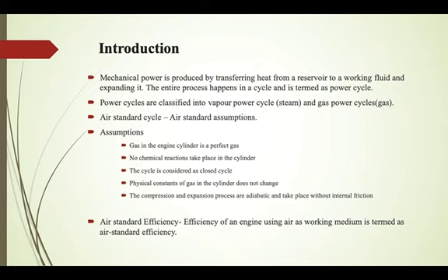Another term is air standard cycle. Air standard cycles are those cycles which work with certain assumptions known as air standard assumptions. The first assumption is that the gas in the cylinder is considered to be a perfect gas, that is, it obeys gas laws. Second, there is no chemical reaction or thermal dissociation taking place inside the cylinder. Third, the cycle is considered to be a closed cycle. Whatever fluid is inside is circulated, and there is no transfer of mass across the boundary.